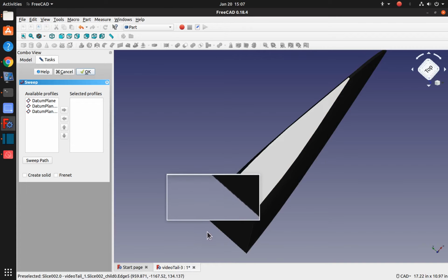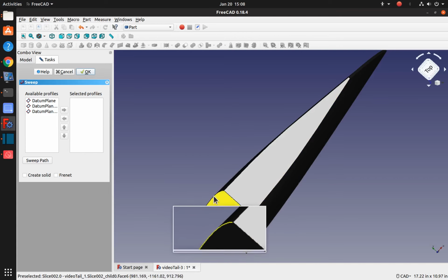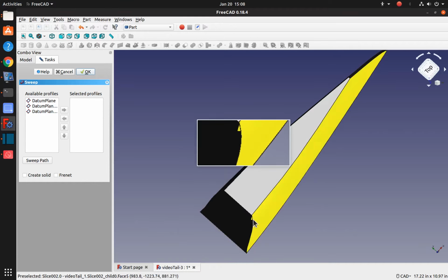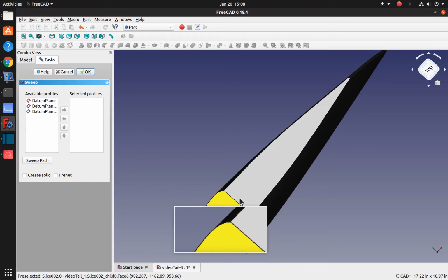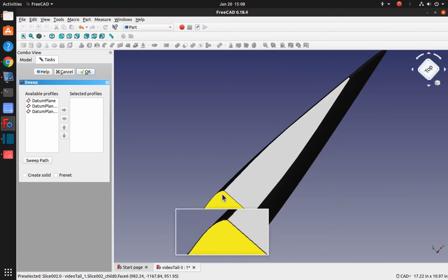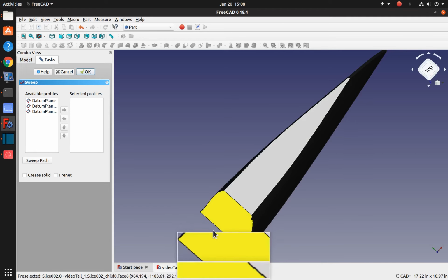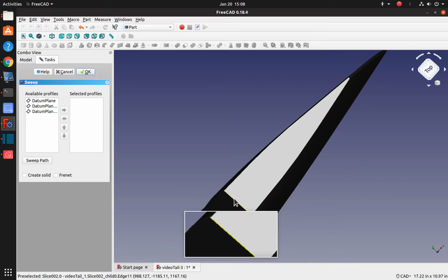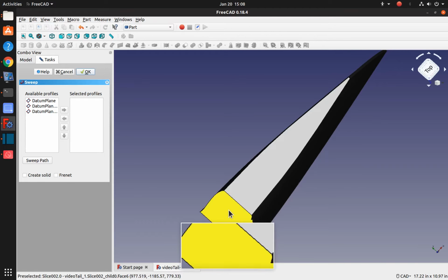I want the very leading edge of the nose to be straight, and I want the elliptical to follow this surface here and this surface here. Now you can see that these surfaces are curved, so we actually have to do a loft instead of an extrusion. What I need to do is make a couple of semi-ellipticals here. I'll draw a straight line along the leading edge where those two semi-ellipticals join, and then I will have to do a loft if I was in something like SolidWorks.